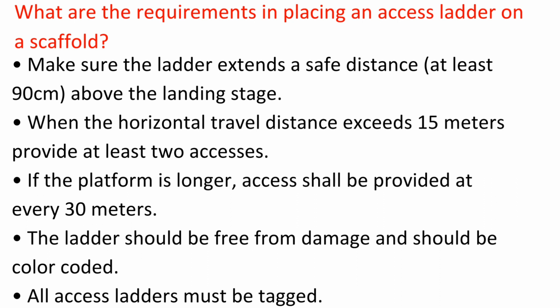When the horizontal travel distance exceeds 15 meters, provide at least 2 accesses. If the platform is longer, access shall be provided at every 30 meters. The ladder should be free from damage and should be color-coded. All access ladders must be tagged.